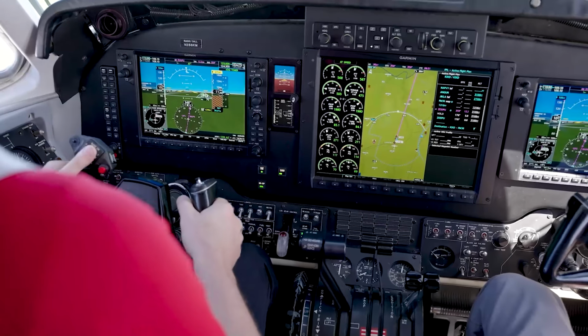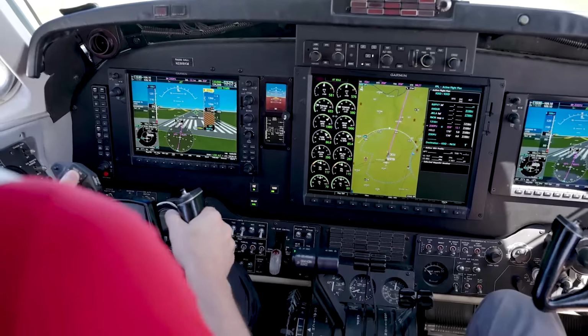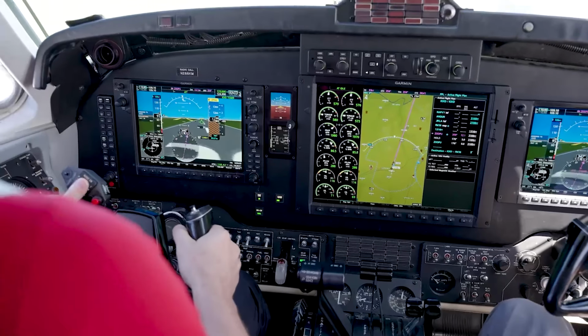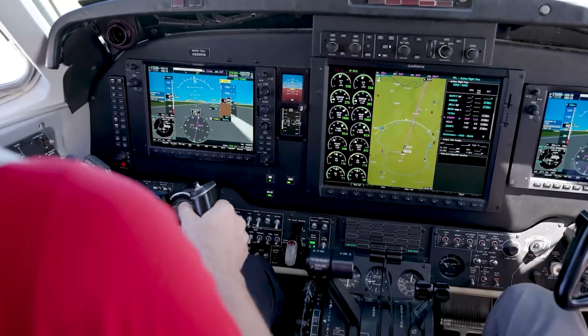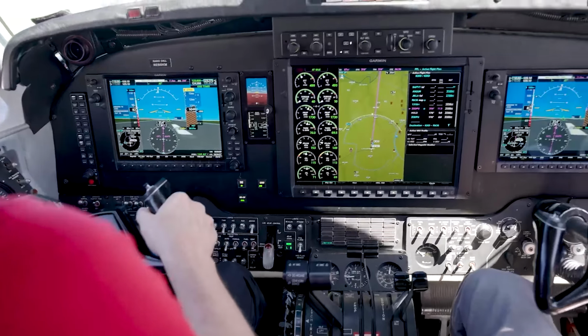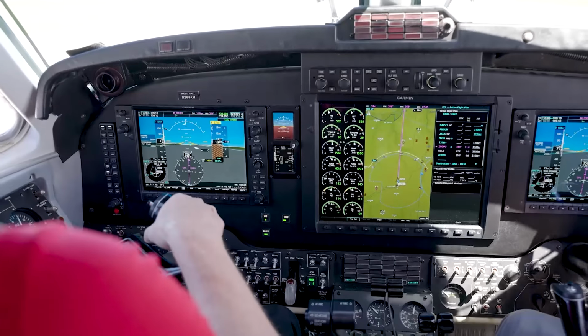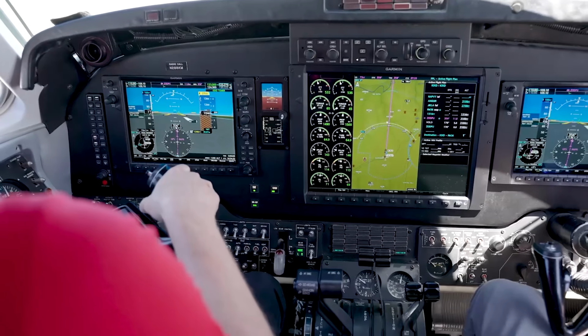If all goes well during the approach and we choose to land, the autothrottle will transition to AT idle as the aircraft crosses through 45 feet AGL, and smoothly reduce both power levers to idle. About 2 to 5 seconds after sensing weight on wheels, it will automatically disconnect, leaving the power levers at the idle stop.